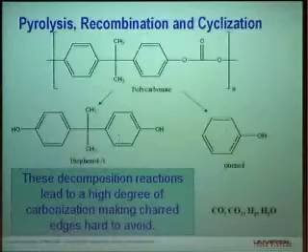You get effluent components that are cyclized, but again, what I'm showing here are the volatile effluent components. And as you're burning through the material, you're creating longer chains of these, which again have a tendency to fold back on each other, undergo recombination, create lots of double bonded carbons, and create more cyclic groups. It's much more difficult to control char with something like polycarbonate.